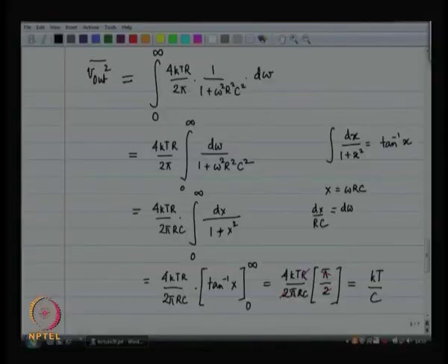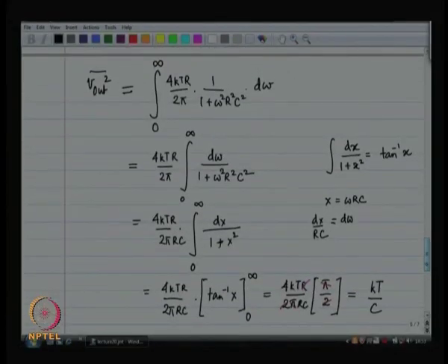So, you are probably all confused, right. We started by saying that the resistor is noisy. Now, I am showing you that for a low pass RC structure, the total noise decreases if I increase the value of the capacitor. What is the story? Next thing to observe is that there is no df anymore, alright. Earlier the noise for a resistor over a given bandwidth is 4kTR df, that is the mean square noise voltage over a given bandwidth delta f.